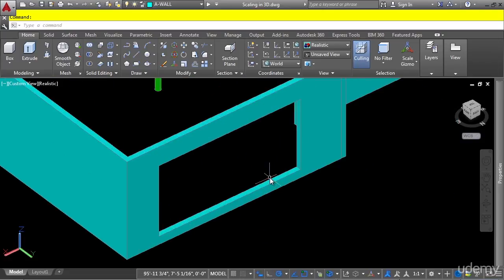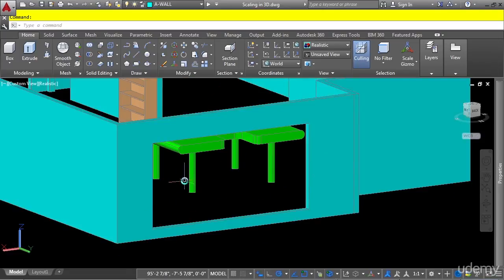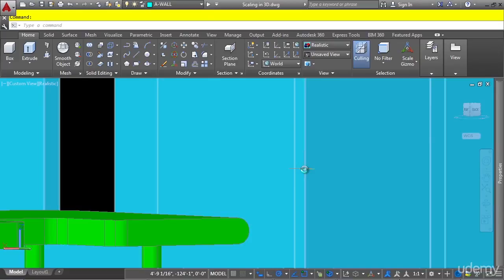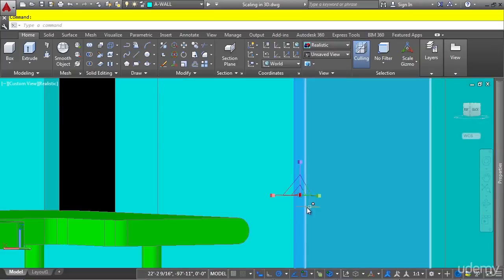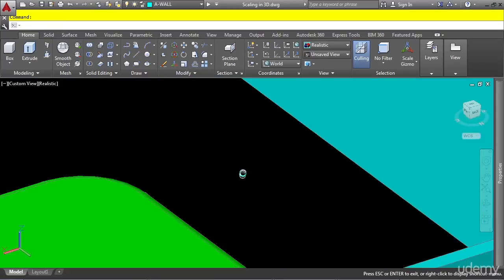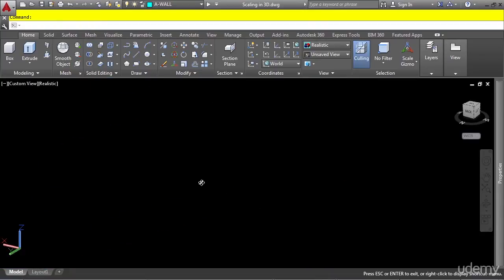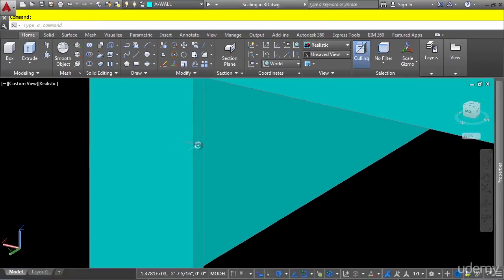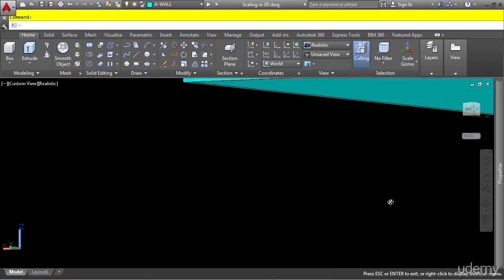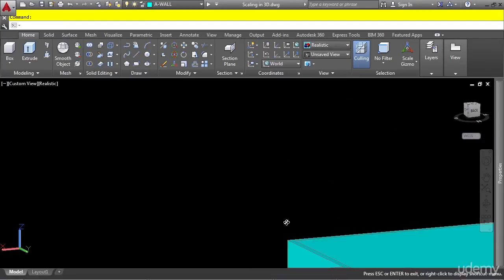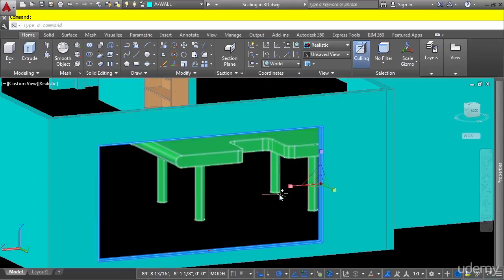We have an actual window we want to resize because it's too large. So what we can do is actually Control select each of the different sides within the window, and then we can use the Scale gizmo to scale them uniformly. We'll hold the Control key down, hover over the face, and pick the different faces. Using Shift middle click, we can get to the orientation of the view to simply select the different faces that we need to select. We'll pick there, and lastly, looking underneath the building, we'll zoom in here and pick this side here. So we have all four sides of the window selected.